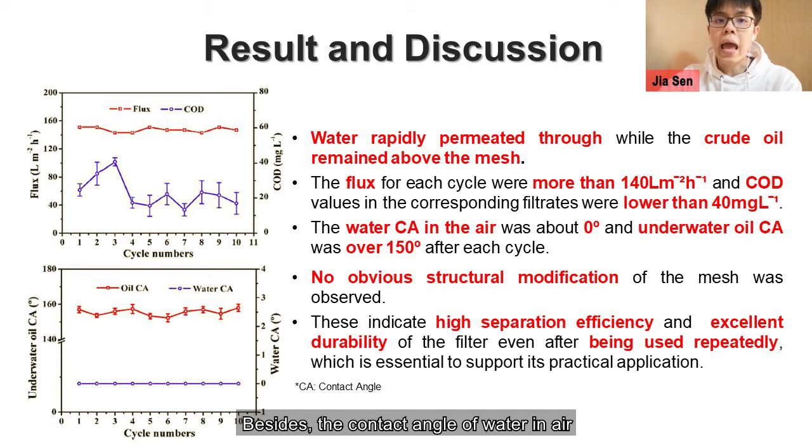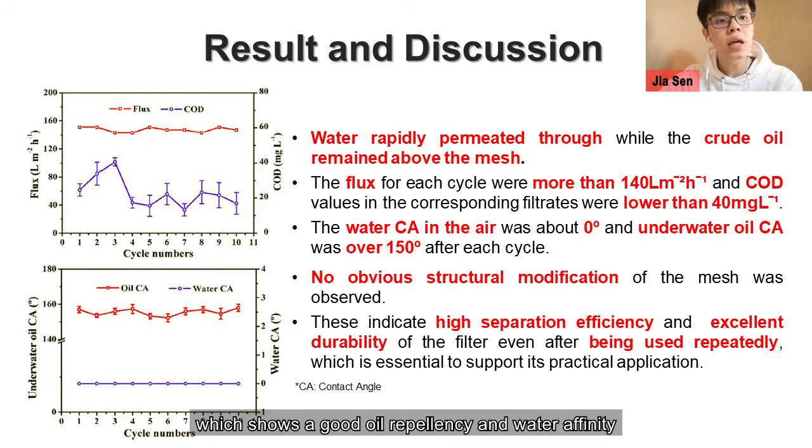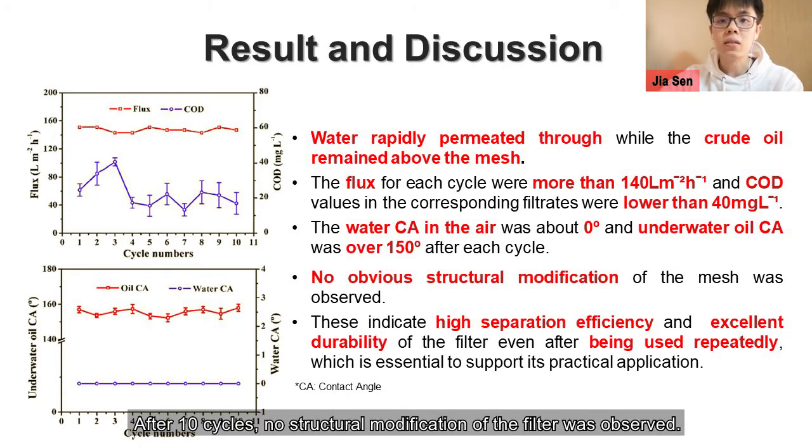Besides, the contact angle of water in air was consistently found to be about 0 degree, and underwater oil was above 150 degree, which shows a good oil repellency and water affinity on the mesh surface resulted by the fluorosurfactant. After 10 cycles, no structural modification of filter was observed.